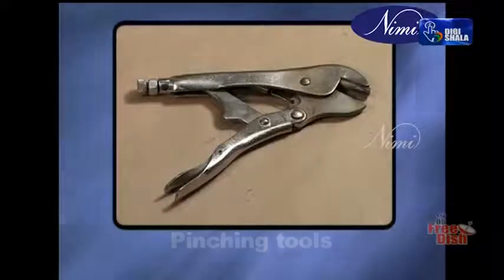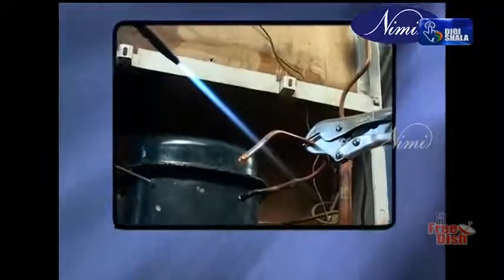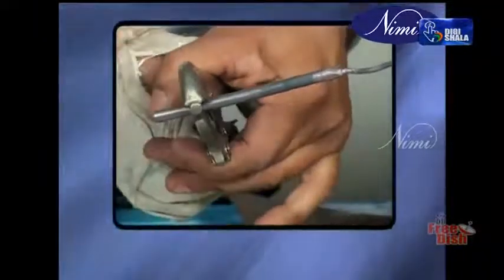Pinching tools. It is used for sealing or closing the diameter of copper tubes. It consists of 2 bars forming jaws and holes of various sizes and are clamped together using nuts and bolts.